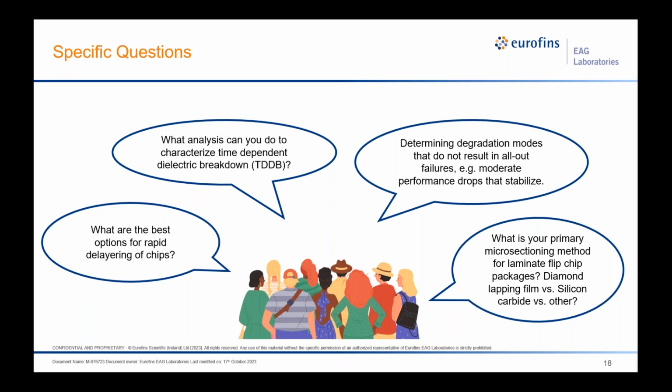Now, the artifacts are things we really need to be aware of. Are we inducing or embedding silicon carbide particles into the sample itself, which may confuse or obscure some of the analytical work? The different types of cross-sectioning methods we have include metallurgical cross-sectioning, which involves the film, silicon carbide and grinding, but that does introduce a lot of artifacts like delamination and cracking. Other techniques we utilize to supplement or mitigate some of those are broad beam ion milling, dual beam FIB, which is a bit more precision based, and plasma FIB, which is another ion based cross-sectioning, but on a larger scale.